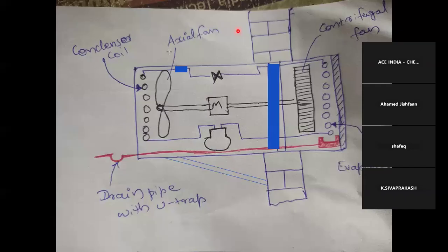Guys, on the condenser side, if any fault is faced on the axial fan, you can see the machine will not work properly, isn't it? In other words, you will not be getting cold air inside the room if the fan is not working on the outdoor unit. You've been seeing that scenario, isn't it? So typically, an axial fan is as important as the condenser coil itself. The purpose is to boost up the heat exchange process. That's it.